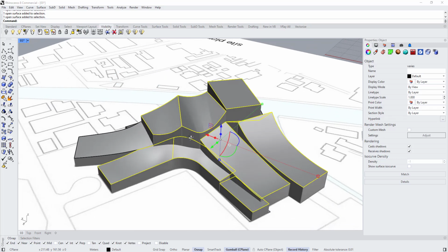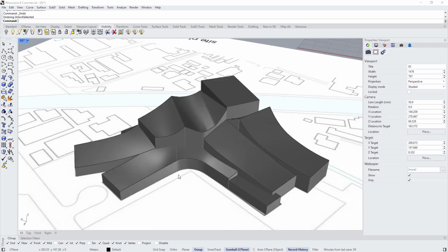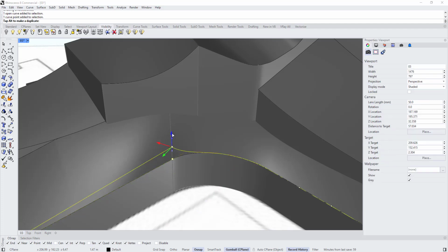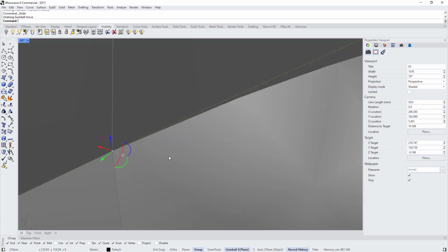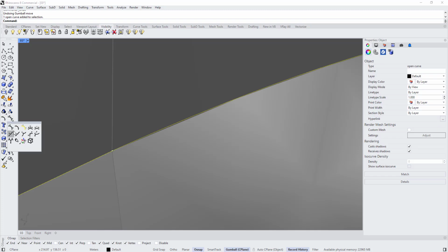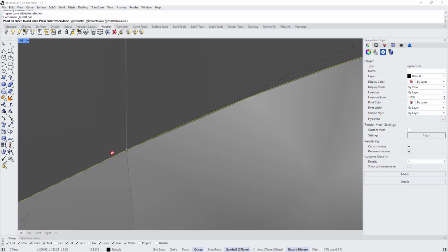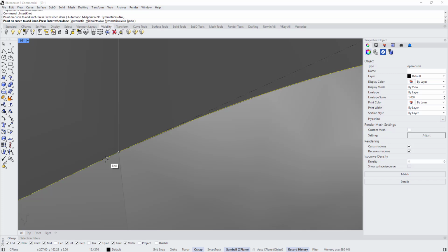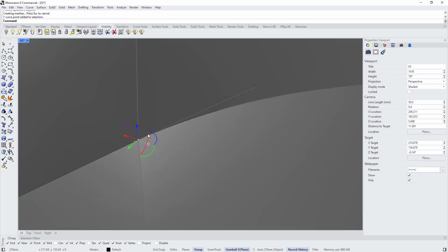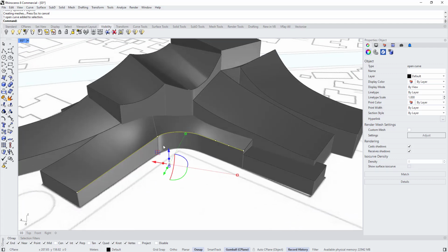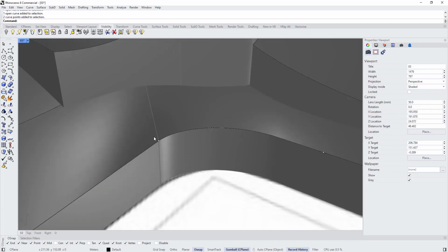Why is this one not one part? Okay, sorry, Control Z. Is this point a kink? I want to delete this point or remove this kink. So I'm going to insert a node at a very, very close distance to this kink here. Maybe right click, then delete this kink so that the curve doesn't deform too much.